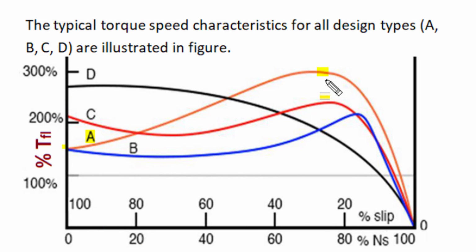Due to small amount of leakage reactance, their maximum torque capability, breakdown torque or pull out torque, is 3 times of full load torque. But this motor got good running performance and full load slip is around 3%. Now standard NEMA design B motor is an improvement on class A motor, and they have deep cage rotor. Due to deep cage rotor, at the time of starting, current becomes just 6.4 times of full load current, and